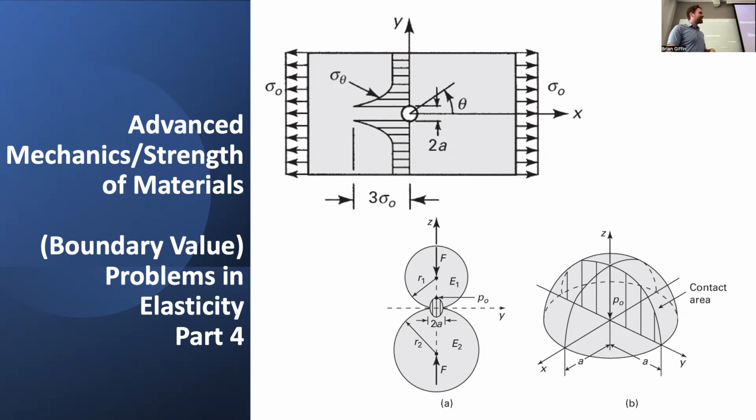And to do that, rather than considering concentrated point loads, we really do have to take that single concentrated load and distribute it out over some finite area. And one way to do that is through this theory of what happens when two bodies come into contact. So we'll talk a little bit about contact stress distributions, and we'll talk also about stress concentration factors and what do you do when you have maybe not necessarily a point load applied to a body, but localized features such as a hole in some large object. What happens to the distribution of stresses in the local vicinity of some feature or deviation from a perfect, homogeneous geometry?